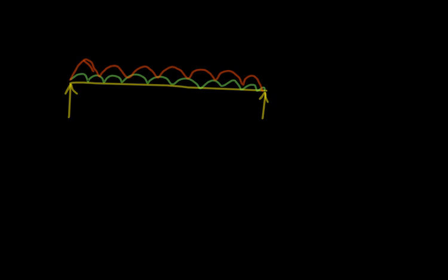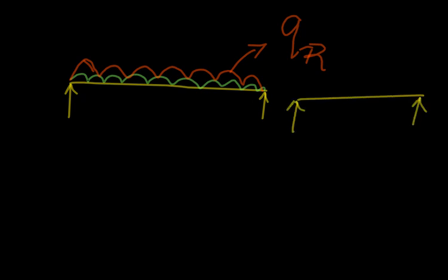That is the residual rate of loading. So that is this unwanted q. So this is q suffix r, the rate of loading that should not exist, but because of the trigonometric trial solution that we assumed, there is a residual rate of loading. I hope you are able to understand the physical meaning of the residual, because residual is unwanted rate of loading. Okay, now I would like to emphasize this point again. Let me draw a simply supported beam. Here we go. Well and good. This is the rate of loading.